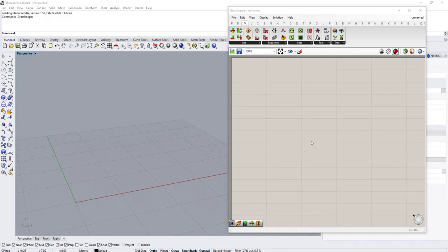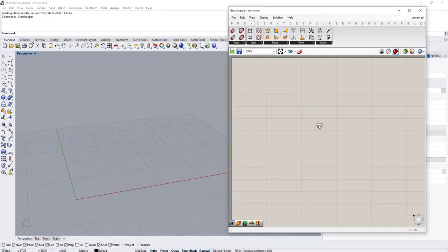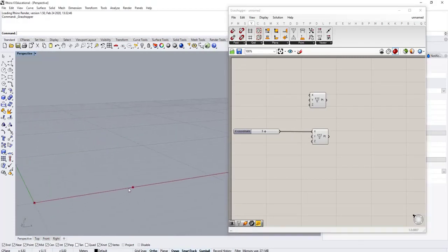Here we want to draw a simple truss. So we can begin with a Construct Point. You can find it under Vector, Point, Construct Point. The first point will be the 0, 0 point. Now we need a second point with, for example, 5 as x coordinate.